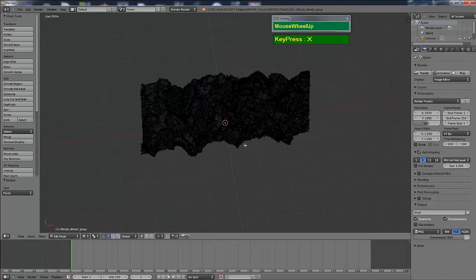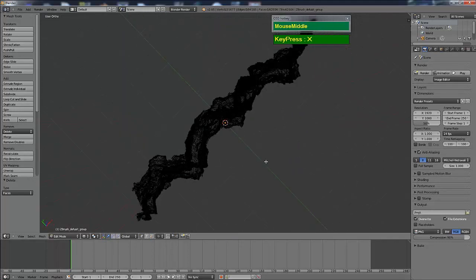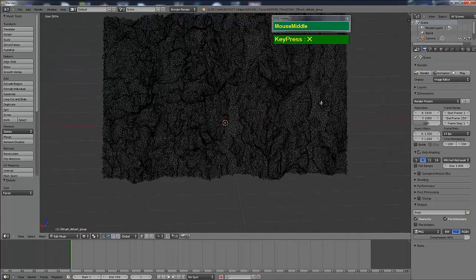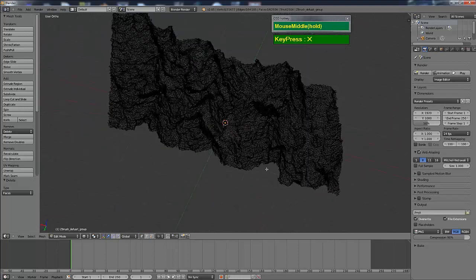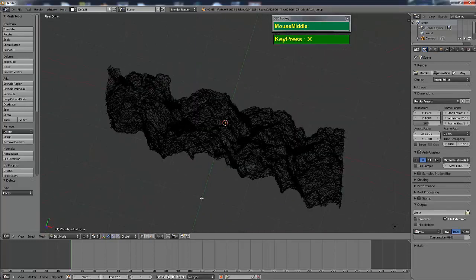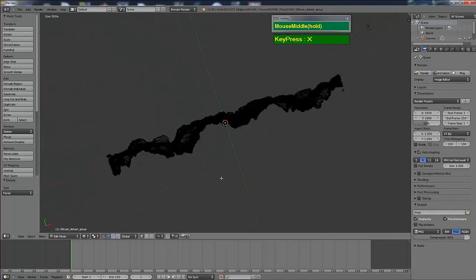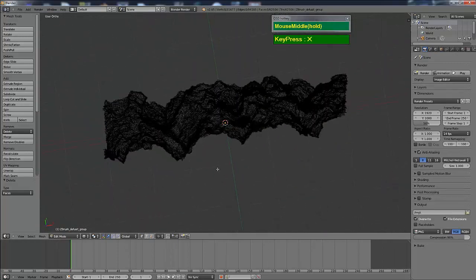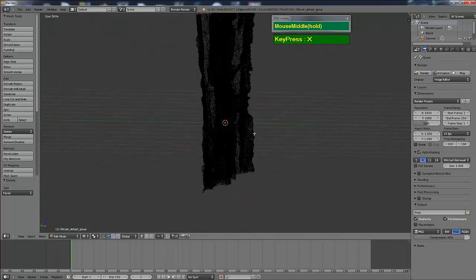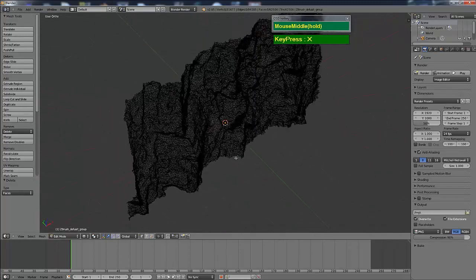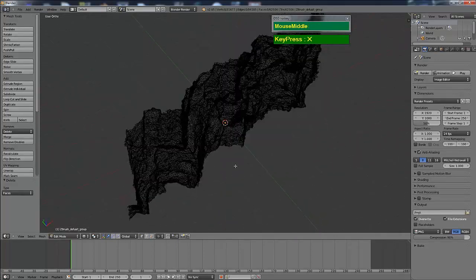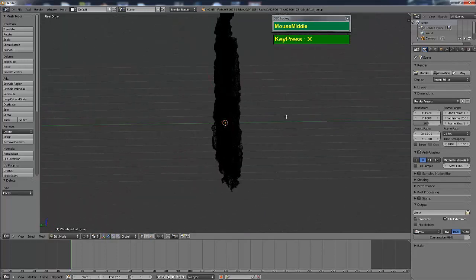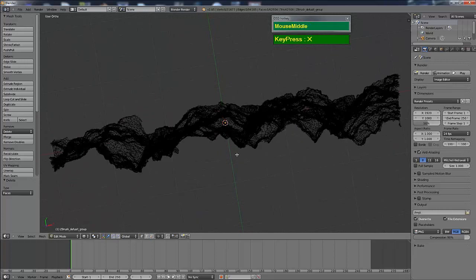Once the edges are trimmed, you'll notice that the 3D mesh object has a very deep textured surface and a lot of overlapping faces, and this will cause a problem later on when you are trying to apply Boolean or trying to model the thickness into these surfaces. So what I'm going to do first is apply a relax to spread out the mesh.